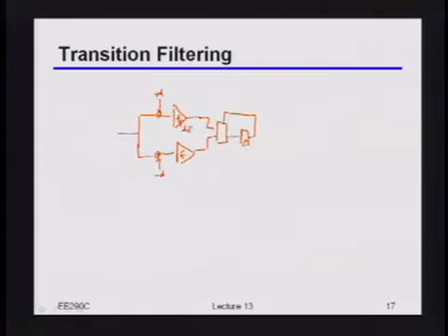Okay, so this again may be your data path. But then what you could potentially do is on your edge path, instead of having all 3 of those samplers, you'd only have 1, right? But then you say, okay, but look, I'm only going to use this when I know that I actually had a clock pattern, right? When I know that I had a 101 or a 010, so that I know that timing information is reasonable. In fact, you can keep on extending this to more and more taps, so that you really only do your timing estimates based off of patterns that you know should have good information given whatever it is that you were doing in your equalizer.